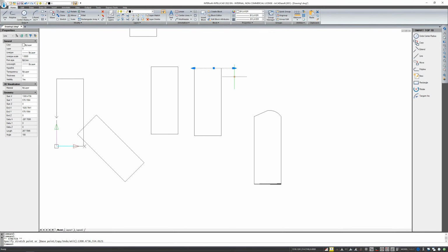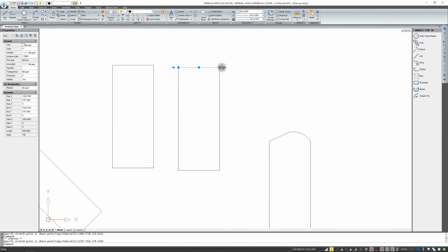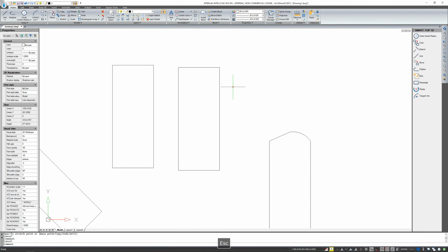If you want to keep an angle, and you use these triangles at the beginning or at the end, you can shorten or lengthen this line accordingly at the existing angle. If you grab the square handle, then unfortunately the angle will no longer be maintainable. Of course, the stretch option will give you such an opportunity, while you can simply select and lengthen the line using these four triangles.